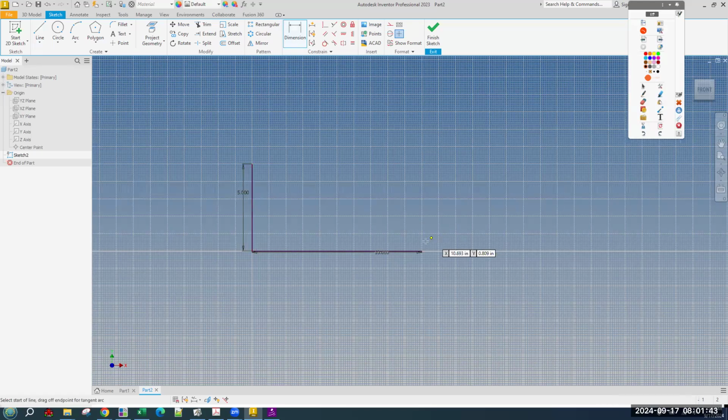And we need another line over here. If you're making a line and know you're going to dimension it, you can see about halfway up the line I'm making, there's a text box that right now says 5.817, which you might not be able to read from across the room. But if that's highlighted, I can just type in the number that I want, and it will make it and dimension it all in one step, which is nice. Okay, and this way I need 1 that way. And I need a new line that goes this way. And the old-fashioned way is this way.